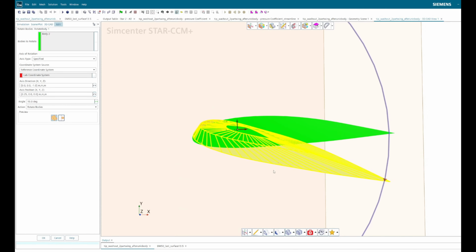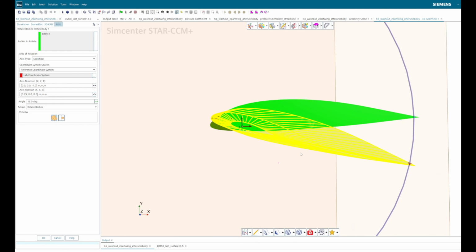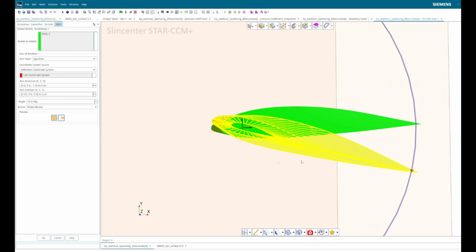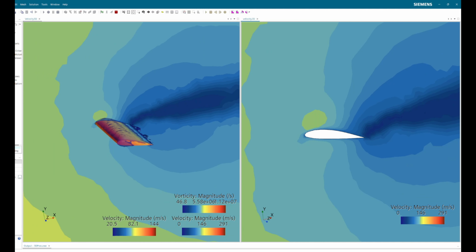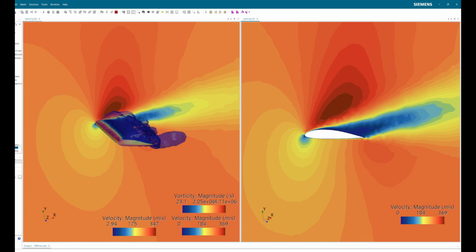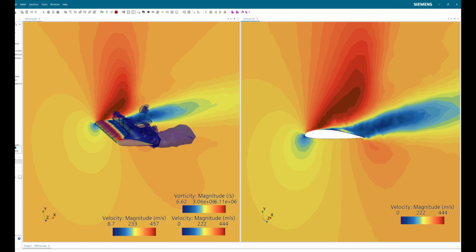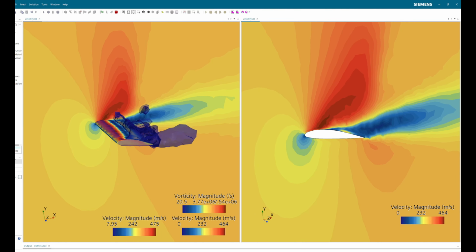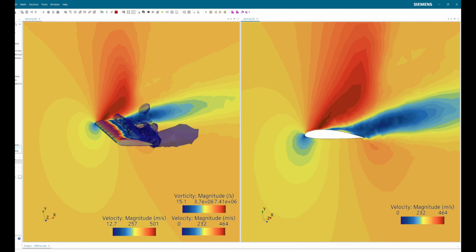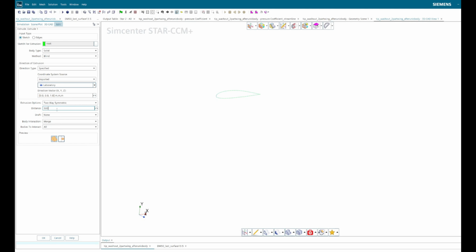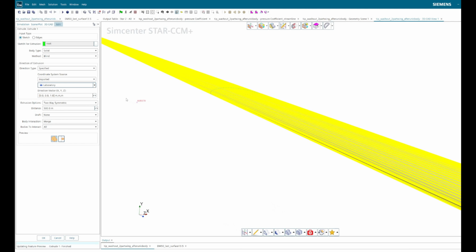This allows me to keep the CM reference point fixed at the quarter chord without worrying about changes caused by varying angles of attack. Since coefficients like CL are independent of velocity and depend only on the Reynolds number, and the Reynolds number variation in my project is negligible, I first compared the aerodynamic coefficients of the 3D model with those of the 2D airfoil section. One point to clarify: in 2D calculations, the airfoil section is treated as an infinite span wing, meaning no wingtip vortices and no induced downwash. This idealization will be reflected in the comparison of the results.